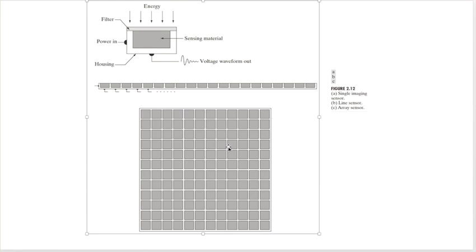Exactly, yeah. So I put a conductive grid and I want to ground it to something. In space, we usually just do it to the outer shell. Okay? And basically, when one of those things hits the metal, metal's highly likely to absorb it, and then it just pulls it away. So we often have to protect the electronics from them. Otherwise, you would get all these event upsets and your system would go bad. Okay?